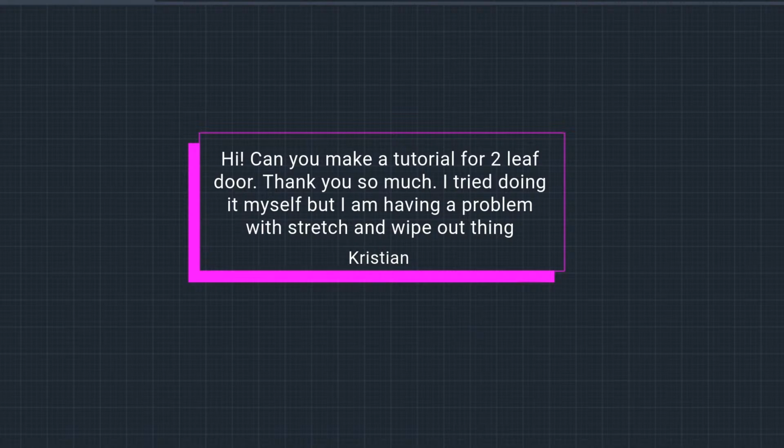There is an exclamation mark, but it simply means that this parameter needs an action, and that's what we're gonna add. But before, I need to select my linear parameter and go to my properties and change the number of grips to 1, because right now I have 2 grips, and that's gonna bring up problems. I only need 1, so that's what I'll do, and I'm ready to add my stretch action.